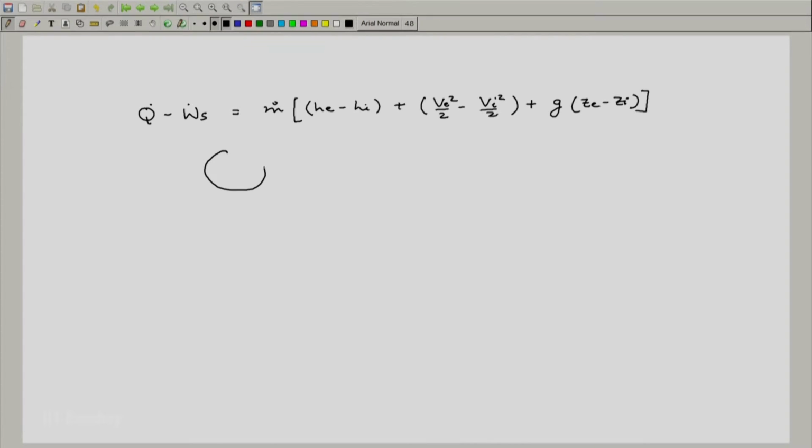And this is the pump. There is an inlet here, there is an exit here, this is the change in pressure, this is how we show it. So inlet is given as 0.1 bar, which is 0.01 megapascal, and this is a typical situation from a power plant where the exit of the condenser is saturated water and we need to pump it either at the boiler pressure or an intermediate pressure in between, where it is mixed with some hot extraction from the turbine. So here we know this is at 25 bar.